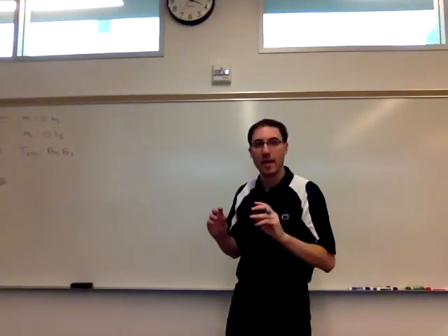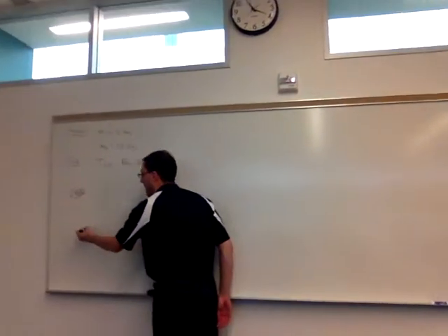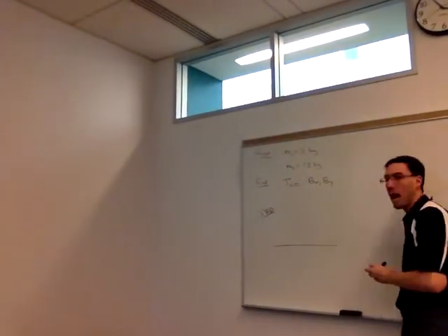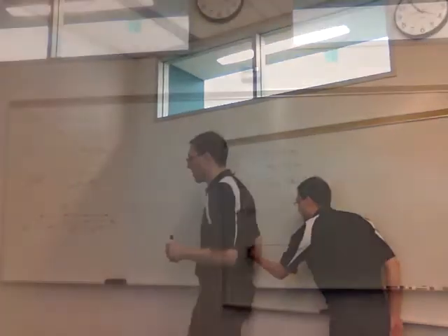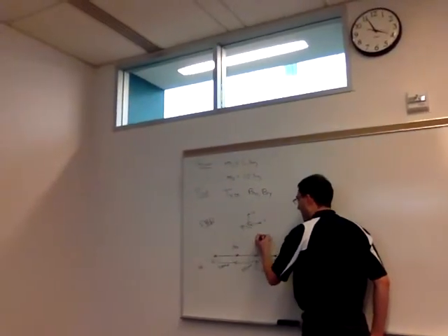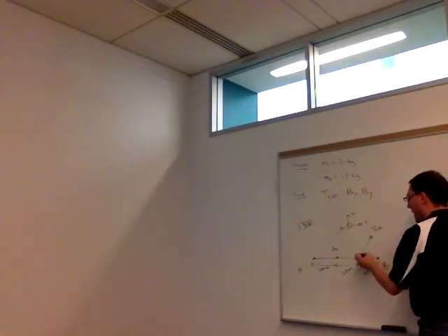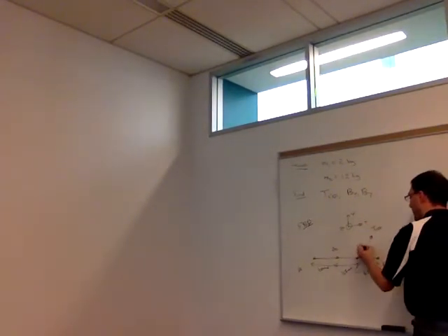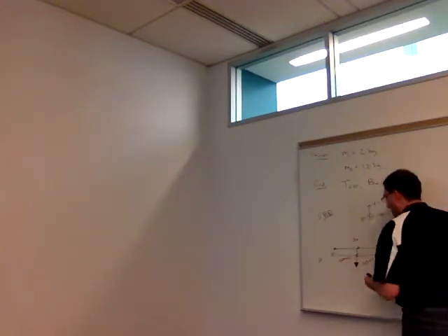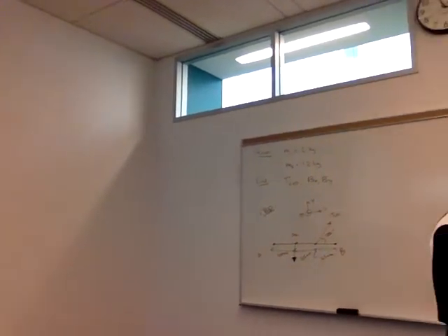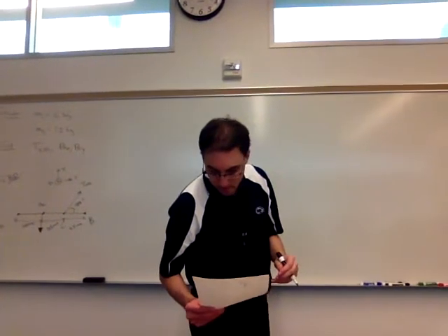So take a couple minutes and draw the free body diagram based on the beam being our object of interest here. Right, so the force from the muscle, or the rope in the structure. We don't know its magnitude, but we do know its direction is 75 degrees. Right, so to 3 digits, 11.8.